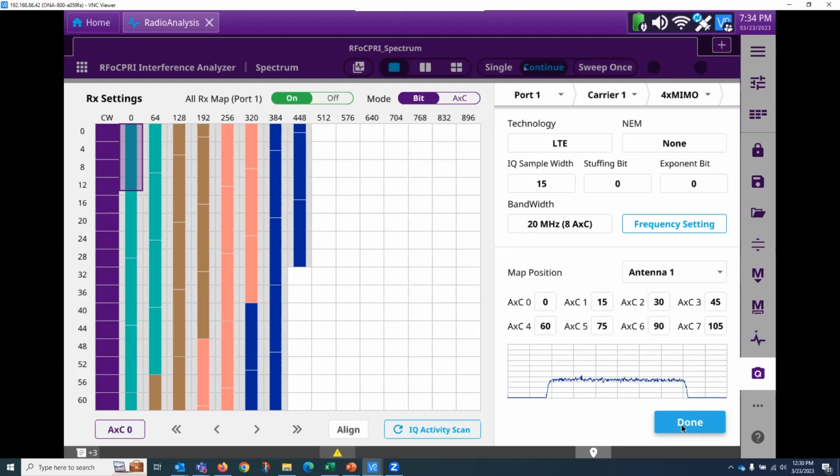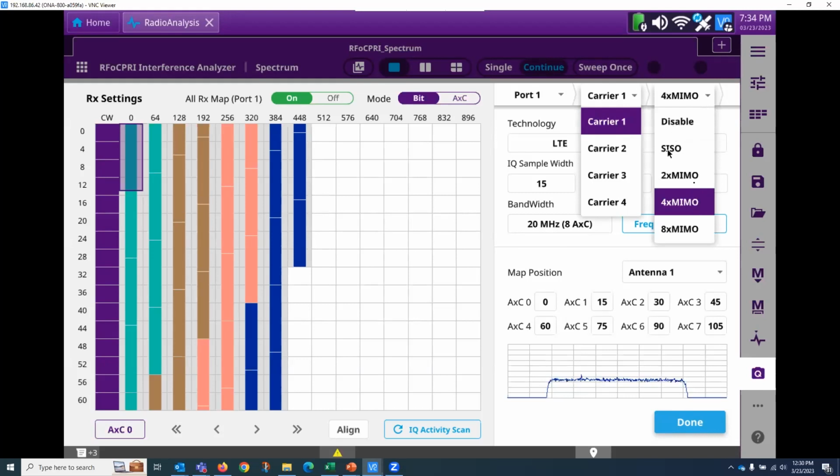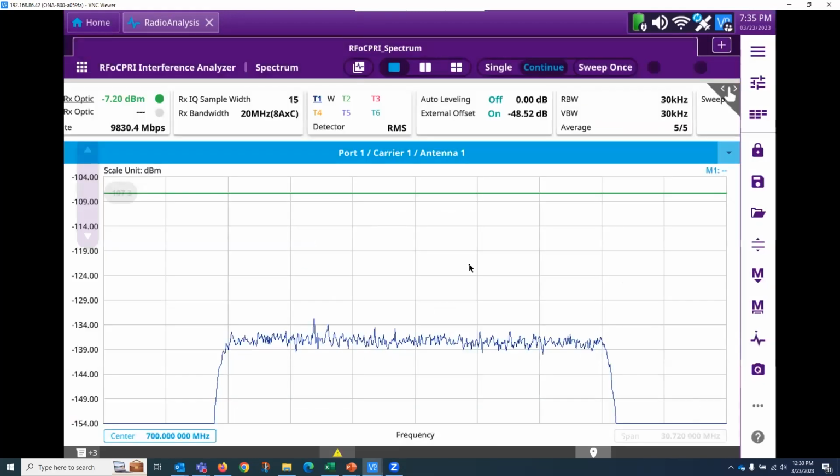And I'm on a single carrier system. We could be on a multi-carrier system. I'm not showing that because I don't have access to that today. And just for clarity, this is a 4x4 MIMO. But as he said, we can do single 4x4 and even up to 8x8 if we really wanted to. My setup does not allow for that. So a quick look, and just to express, this is an actual live signal we're looking at with some RF coming in. I've offset some of the frequencies with some cooperation, so we're not going to pick up a lot of user traffic on purpose because that's not fair when I start turning on PIM stuff. I'm trying to be nice to all the players out there.